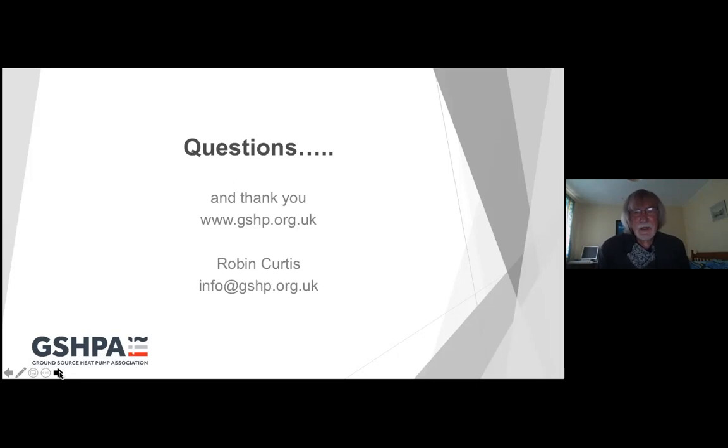This is acquired knowledge. But what I would say is, everything that I've talked about today, you can apply to shared loop systems. Just track your way between wherever the heat pump is and your ground loop, and make sure that the combined effort of the pumps and the individual heat pumps is going to be enough under the worst case conditions to circulate in the active elements, to get your Reynolds number where you want it to be, and to get enough flow rate through the heat pump.